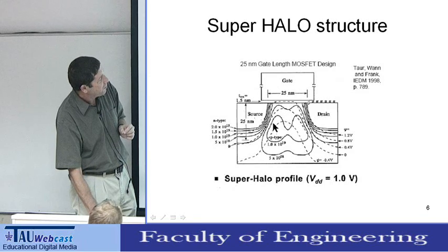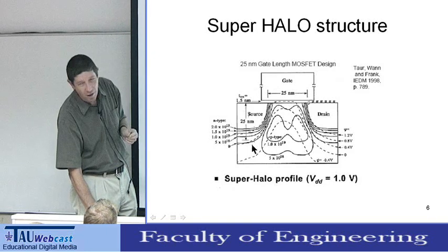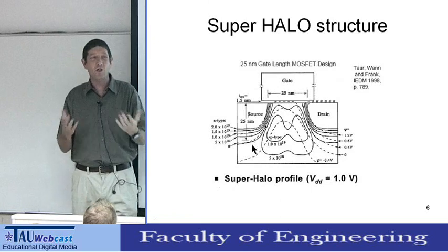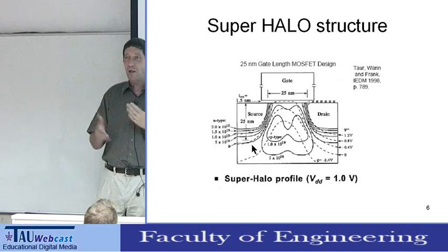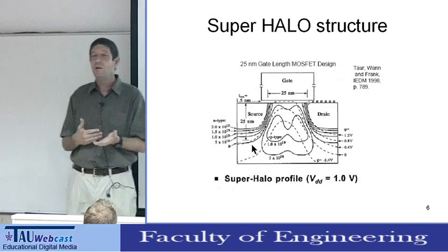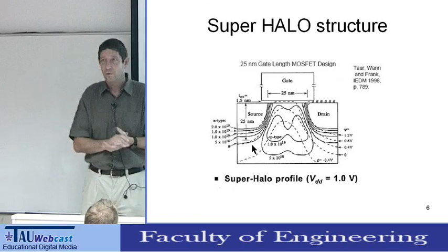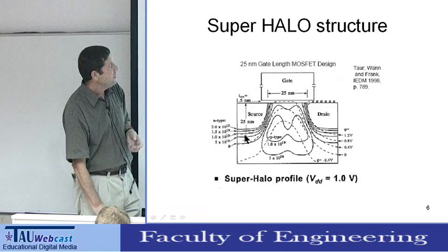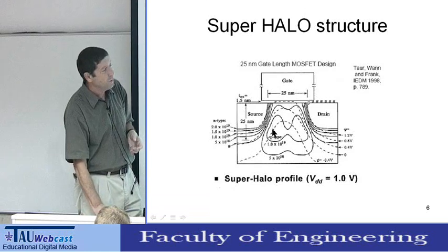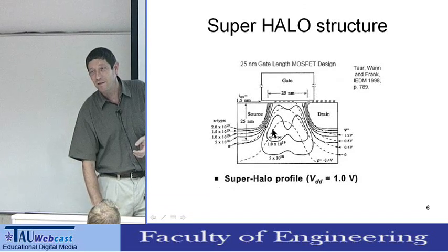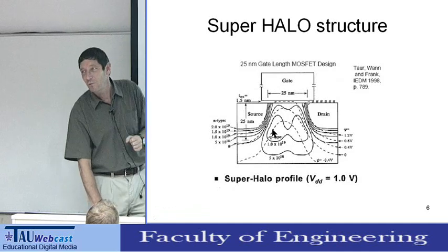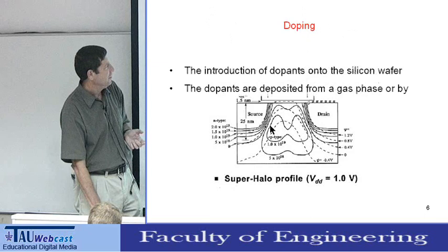However, you don't want to put P+ everywhere, because you don't want N plus P+ junctions, because they are very leaky. If you remember the equation for leakage current in junctions, for heavier doping, you have more leakage. Another reason is that if you have heavier doping, you have more defects because of the ion implants, and if you have more defects, the minority carrier lifetime becomes shorter.